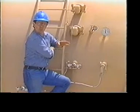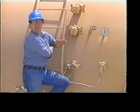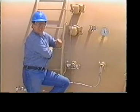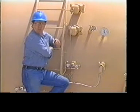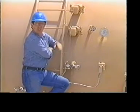The temperature of the emulsion in the inlet section should be kept around 140 degrees Fahrenheit, so the temperature of the fluid in the treating section around the grids never falls below 70 degrees. Should the temperature fall below this level, the grids will not be as effective treating the emulsion.